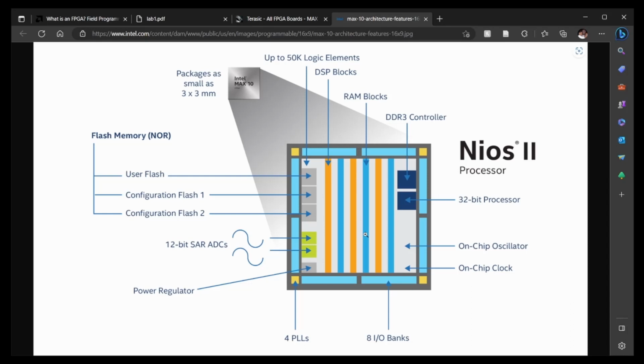Bear in mind that when you are done with your design, what you have done is to describe how the hardware will be implemented and what the software will do. The compiler for that particular HDL, hardware description language, will take what you have said and compile it. I shouldn't use the word interpret because it's not an interpreter. It compiles your instructions into a hardware specification and a hardware netlist and actually burns that onto the FPGA. Better still, we'll actually implement that on the FPGA.